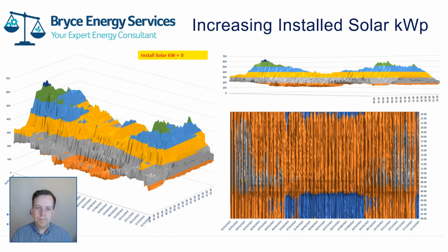Now in future, a lot of this surplus will be associated with EV chargers and consumed by EV chargers, which is fantastic. But the local grid may not be able to support all this export. So you need to consider what is the point of installing too large a solar if you cannot consume all that electricity on your premises.